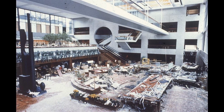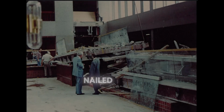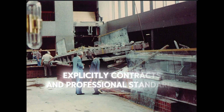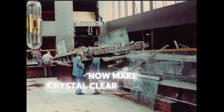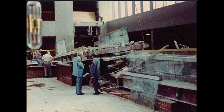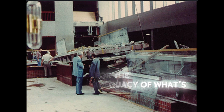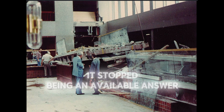concrete ways. First, responsibility for connection design got nailed down explicitly. Contracts and professional standards now make crystal clear who checks a shop drawing change, and that the engineer of record retains responsibility for the structural adequacy of what's actually built. "I assumed they checked it" stopped being an available answer.